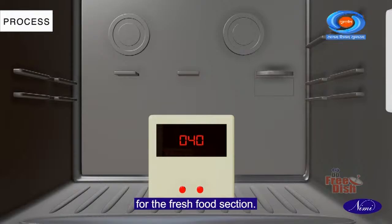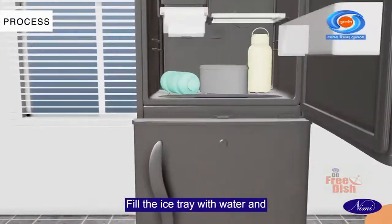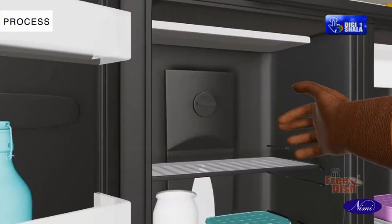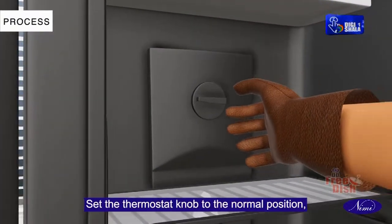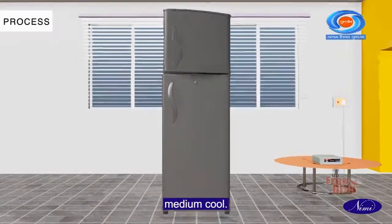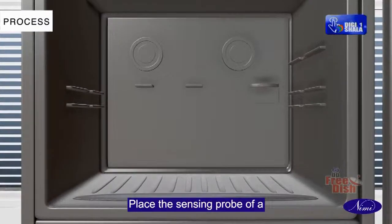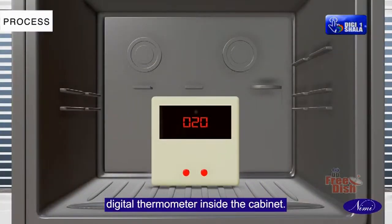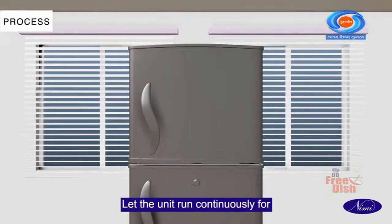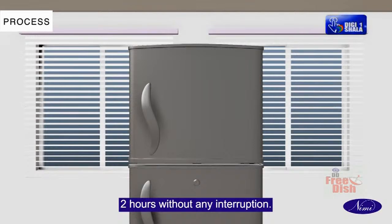Fill the ice tray with water and place it in the freezer compartment. Set the thermostat knob to the normal position, medium cool. Place the sensing probe of a digital thermometer inside the cabinet. Let the unit run continuously for 2 hours without any interruption.